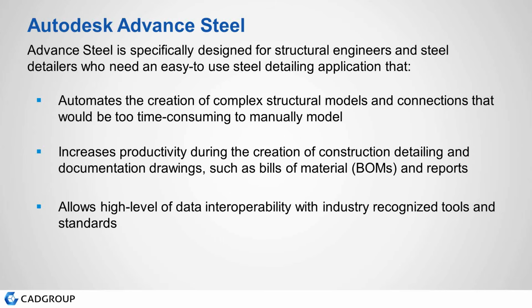Most of you guys use Inventor because Inventor has got a module called Frame Generator, a fantastic program, fantastic module when it comes to doing welded frames. But as soon as it comes to doing frames that have got bolted connections, that's where it doesn't have the automated bolted connections. If you manually go and put in bolts and so on, the assembly size becomes large, and that's a pain. But also, when it comes to doing the detailed drawings, there is no automated process. You'll have to manually do the detailed drawings.